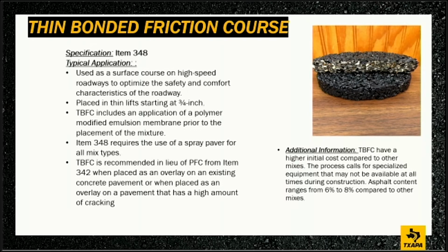Yep. And spray paver, that means it requires the use of a spray paver, okay? So thin bonded friction course is recommended in lieu of a PFC when item 342, that's PFC, is placed directly on an overlay of an existing concrete roadway. Again, utilizing different types of material to bond that surface course down.